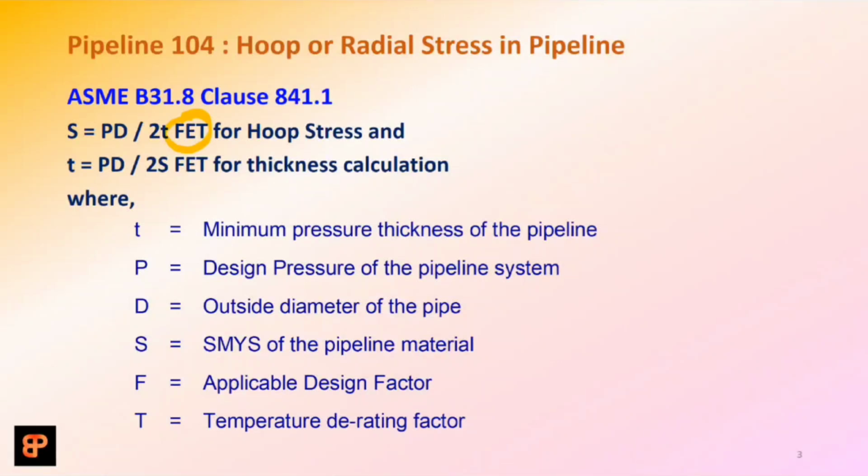Because whenever we are doing any design, we always consider the strength of the material which we are going to manufacture it from, and we apply a factor of safety, such that even if it sees the maximum desired load or design load, there should be some margin in its strength.